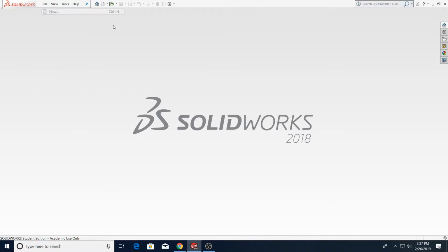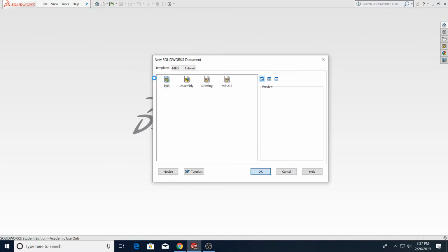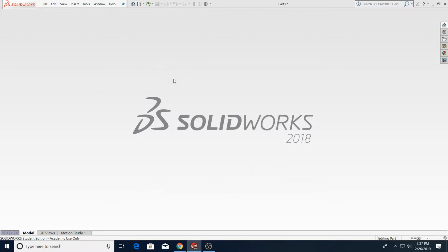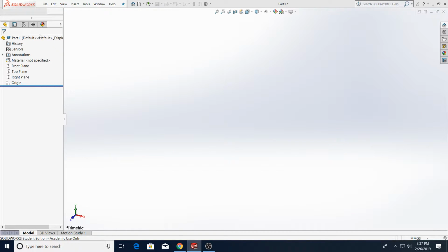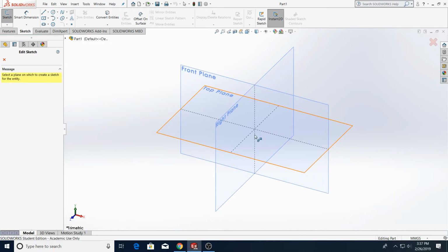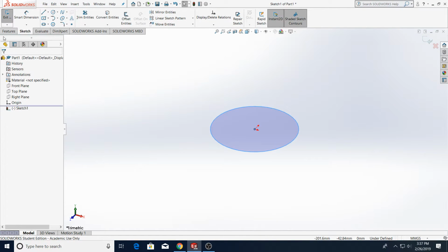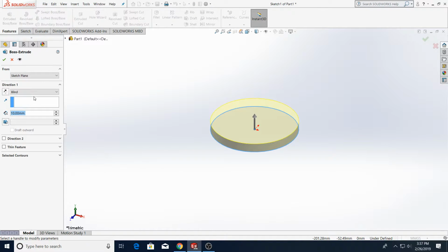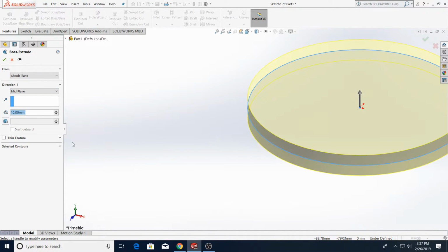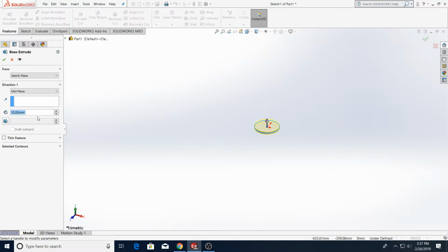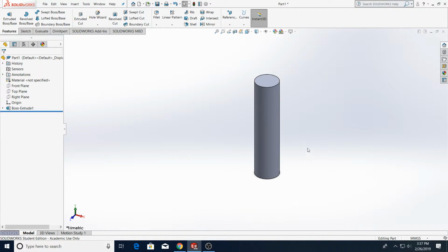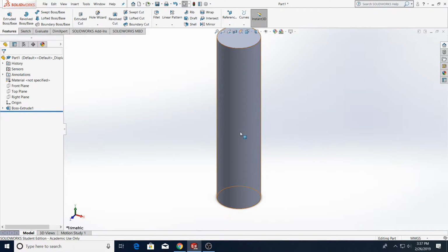The answer to that question can be approached in a couple of different directions. One way would be to draw a rectangle on some sort of top perspective. For example, let's say the fuselage looked like this, and we had a mid-plane extrusion of, I don't know, 400. That seems about right. So one way to approach this would be to create a plane on which to draw from the top perspective and then cut a rectangular cutout.